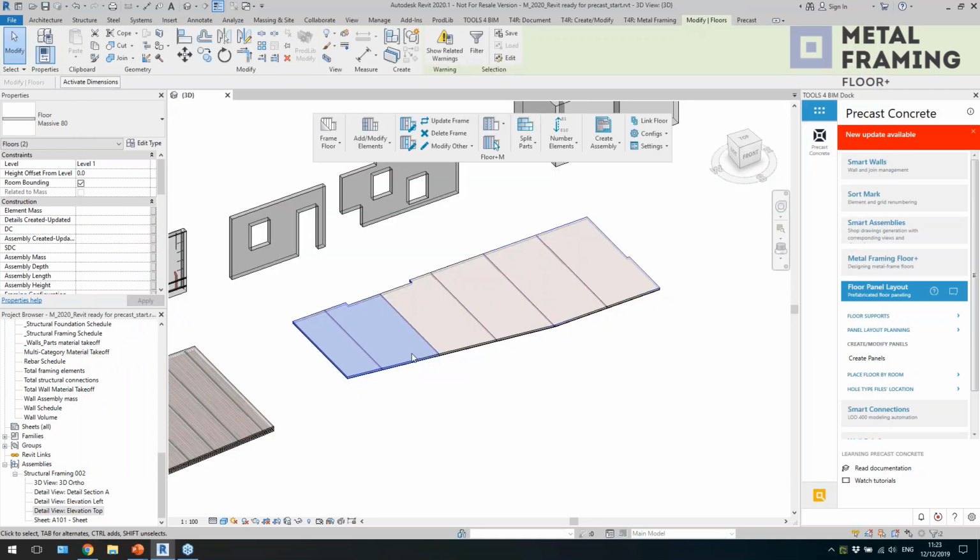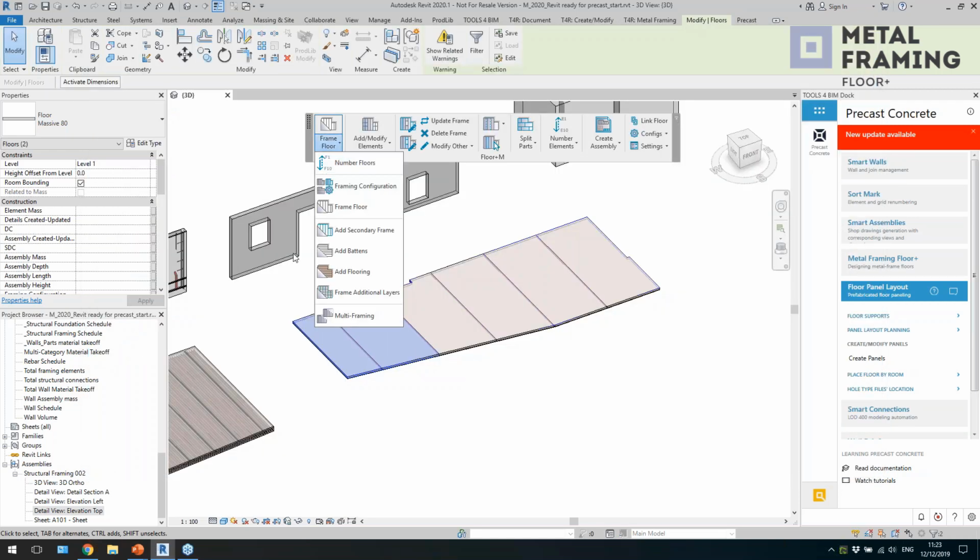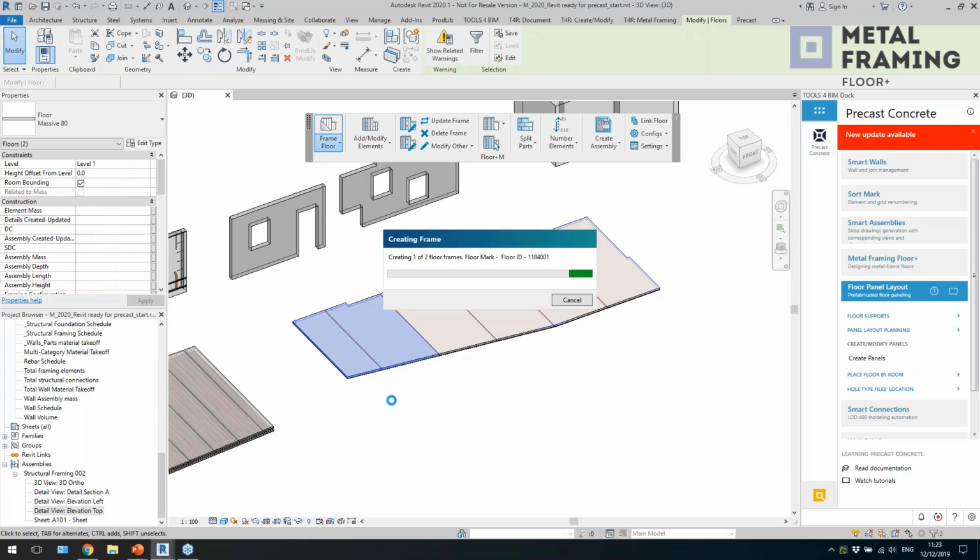So when I have this kind of configuration, I can assign this configuration to this wall type, and then just add them, and they should follow the shape of my slab, and then just distribute based on the rules which I have used.